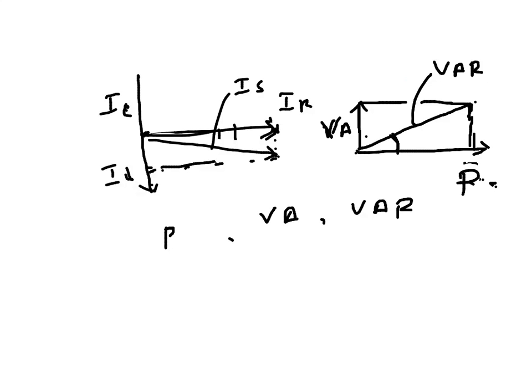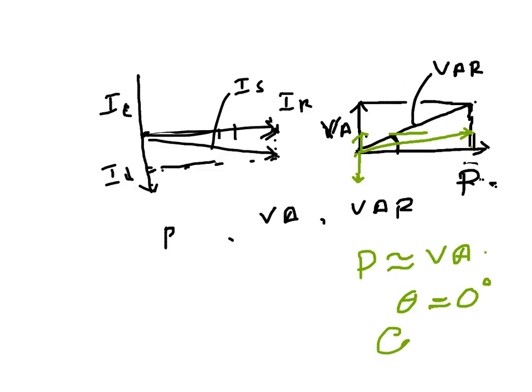Now as we saw in power factor correction, a capacitive load was connected in parallel to reduce the inductive power, so that we could have a little bit of capacitive power there, in the opposite direction, so the resultant is less, and if the resultant is less, we would have a smaller angle, and VAR will be closer to P. So P would be closer to volt ampere reactive, since theta is small, theta is close to 0, that was the target, and that would mean cos theta would be close to unity, close to 1, and that was achieved by applying capacitance in parallel to the inductive load.